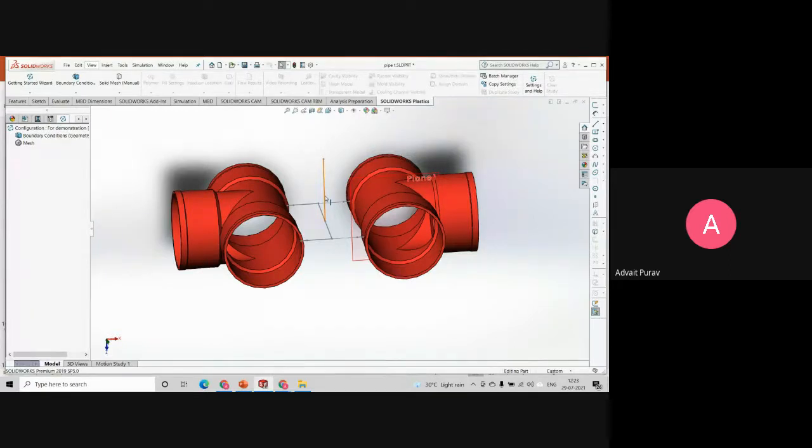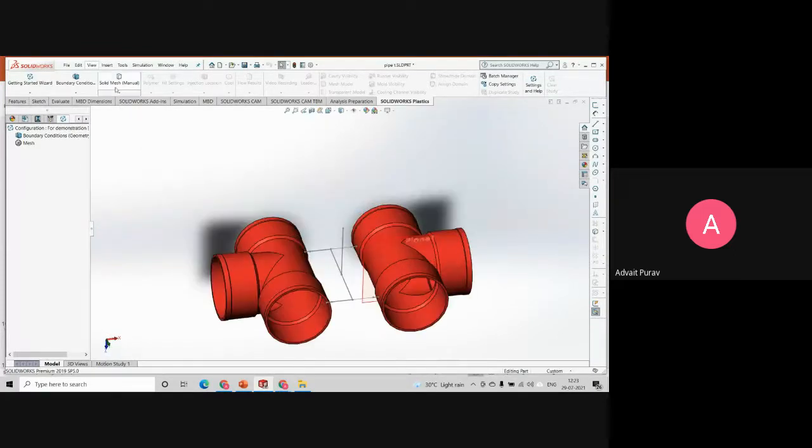whenever you want to run a cooling analysis in a particular FEA software, तो आपको कूलिंग मेशिंग ही करना पड़ेगा, जिससे आपको एक एक्यूरेट रिजल्ट मिले। शेल मेशिंग भी कर सकते हैं इसके लिए, बट उसके लिए इतना एक्यूरेसी नहीं मिलता। और बेसिकली शेल मेश is a 2D mesh, as I told you before, and it will just mesh the outer surface, and not give the right kind of result to us. So solid meshing चालू करेंगे इसमें।